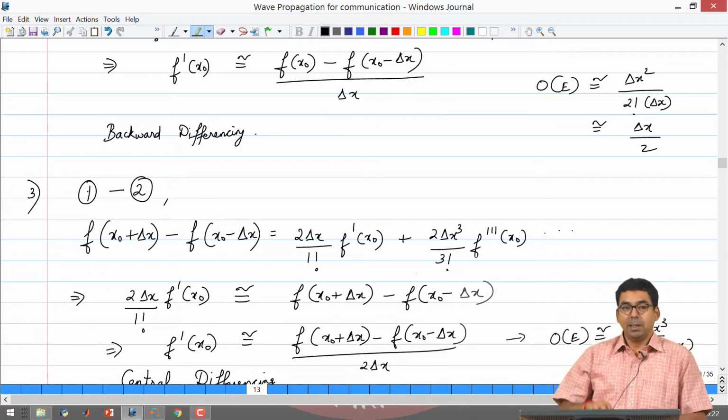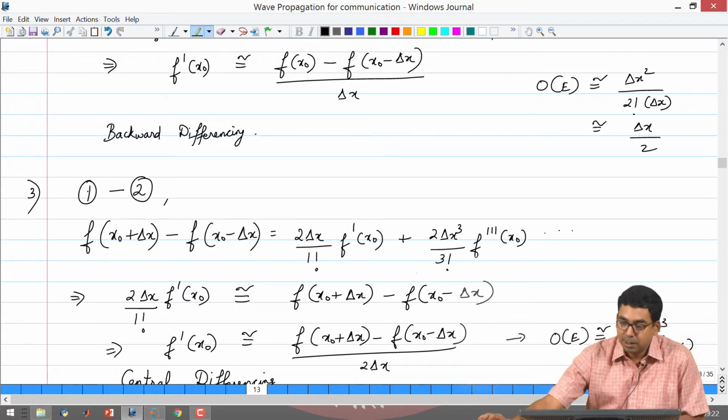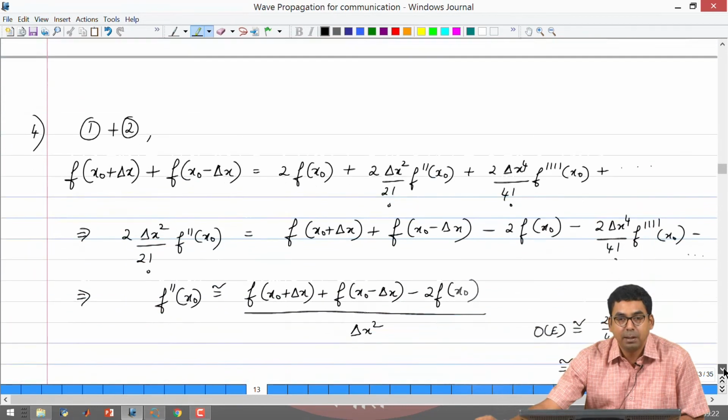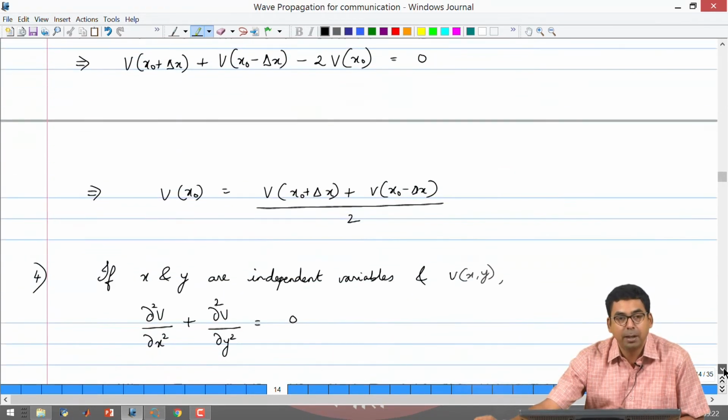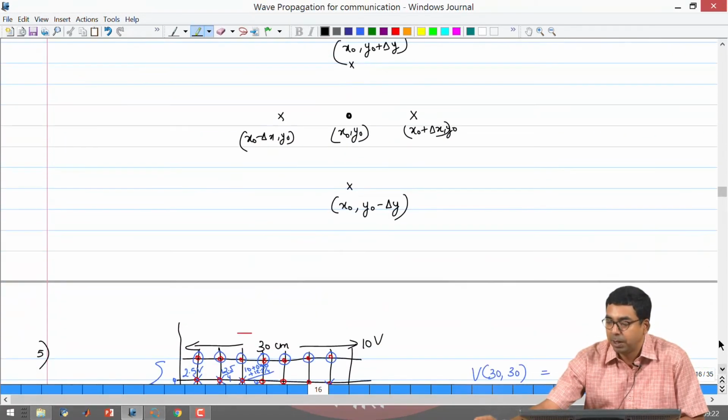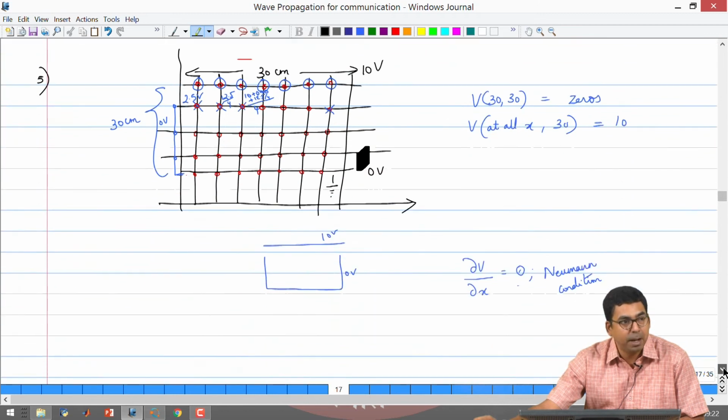The telegrapher's equations were 2 in number. Once we finish that, the remaining parts are going to be a breeze, because you will have a visual understanding of what the telegrapher's equation actually mean. The difference between the wave equation and the telegrapher's equation is, the wave equation is decoupled, that is, the voltage is there on one side with respect to time you take derivative, on the other side you take with respect to space, but you do not observe what is going on with the current at the same time, alright.